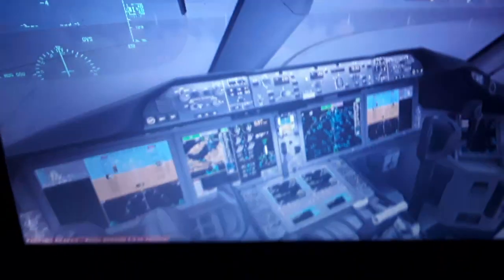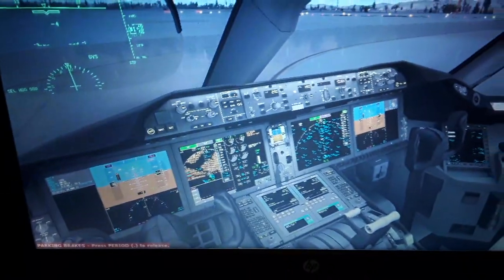I'm going to start with the primary flight display. The display shows the indicated airspeed, the airspeed selected from the autopilot flight director system panel, the ground speed, the radio altitude above ground level, the barometric pressure of the outside atmosphere, and the target altitude selected from the autopilot flight director system panel, the barometric altitude above sea level, the vertical rate of climb or descent of the aircraft in tens, hundreds, and thousands of feet per minute.